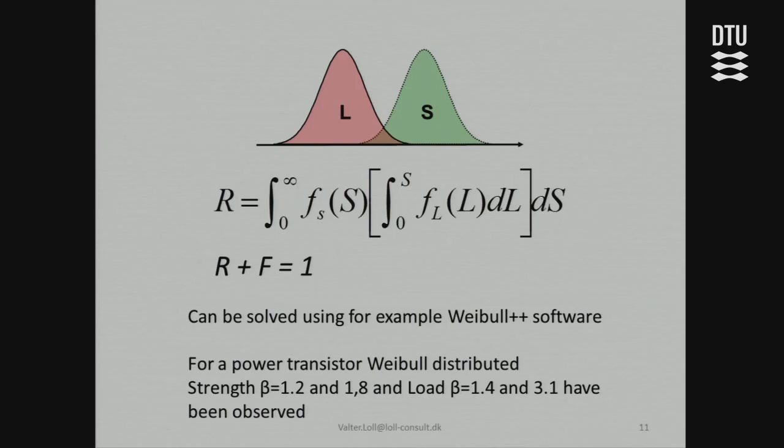No, the curves that I showed you also exist for other distributions, Weibull distribution. So these curves exist. But the thesis at the Danish Technical University showed that the approximation used by O'Connor, and I think also by Carter, is not precise.